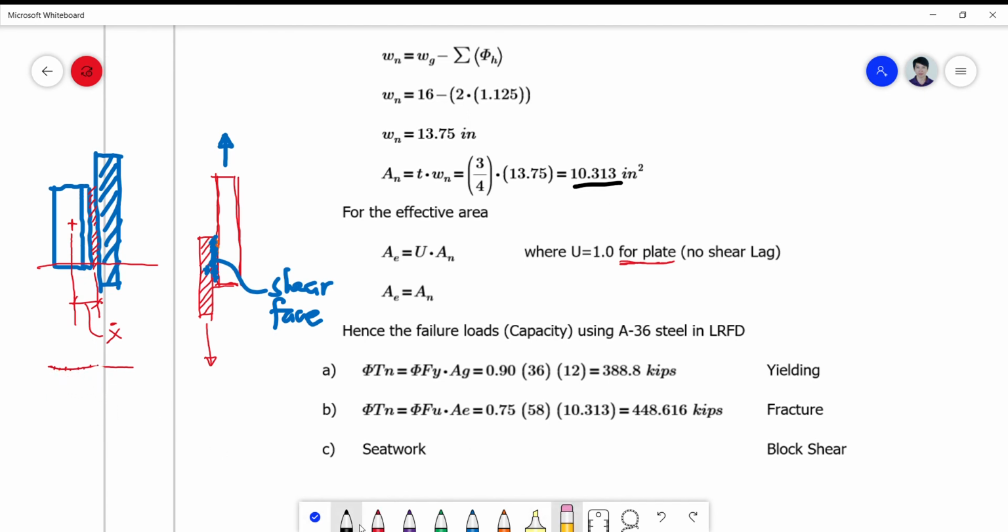This has a high concentration of stress, and it reduces like this, such that the effect of your total force T here will cause a varying distribution of stress, making your P over A, your T over area, erroneous, because it is concentrated more on the centroid rather than far from the centroid.